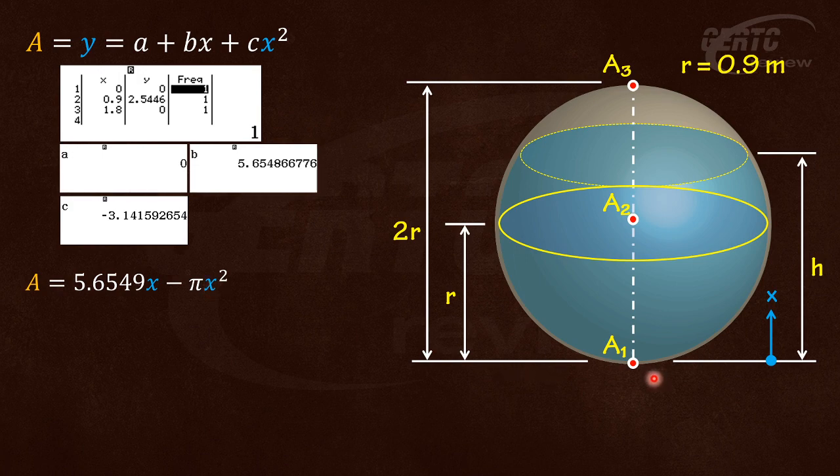Remember hydraulics, when we are asked to solve the time to empty the tank, the formula is integral of area dH. That area is this. And most students have difficulty how to get that area. Your x is a function of the head of the orifice, the head. All right. So that's how widely used is this function.